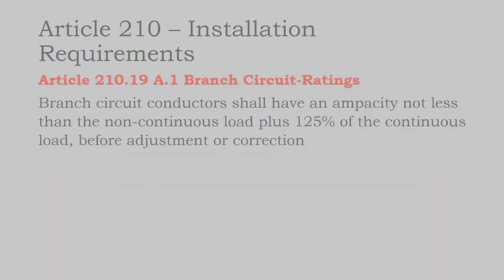And so on continuous loads that are under regular continued use, you will apply safety factors because those cables are under continuous current. They're always on, they always have some heat in them.